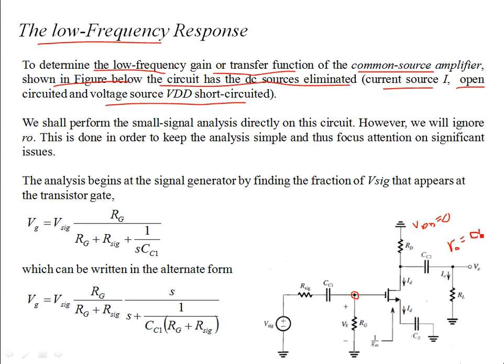So in the common source configuration, the small signal resistance between the drain and source is infinitely large, so it's open circuited. The MOSFET itself is being modeled at the source by a resistance of 1/gm, in ohms. There is an analysis done in section 4.12 of the course text if you want to have a look.